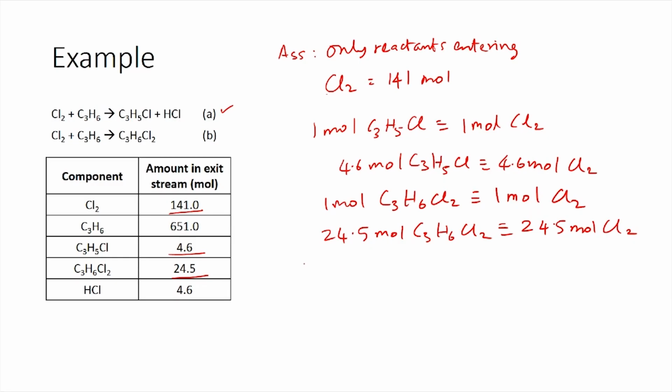So now that we have calculated these, we can calculate the total amount of chlorine which is fed, which is the input. So we can go back to the balance equation which we had, which is input minus output plus generation minus consumption equals accumulation. As the process is at steady state, we will have accumulation to be 0. Chlorine is not generated, so you have only consumption. So you end up with input equals output plus consumption.